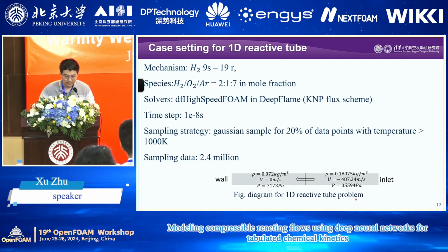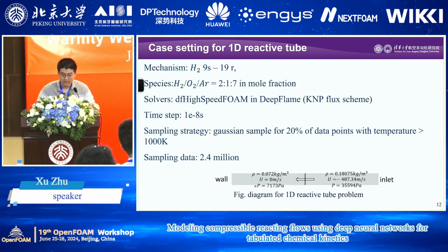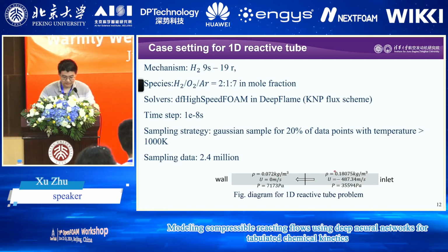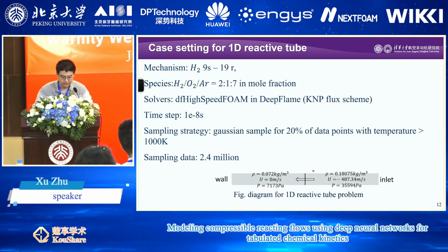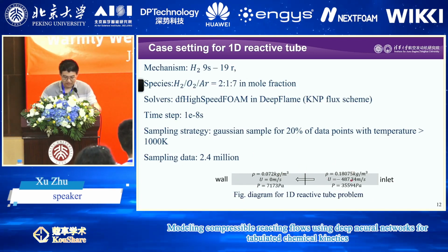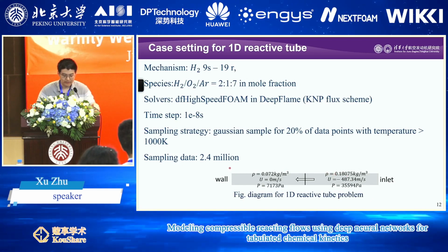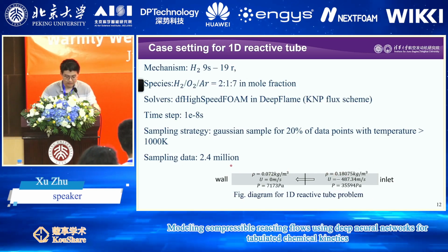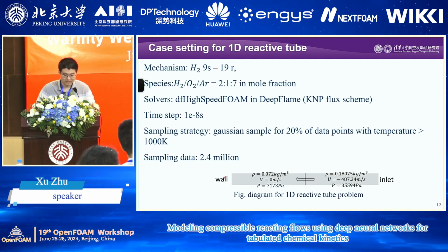On the right side is the high pressure and high speed flow, and on the left side is the low pressure air. When you remove the discontinuity, you will see the gas propagate to the left, and when it hits the wall, due to the stagnation process, the temperature and pressure will increase vastly,